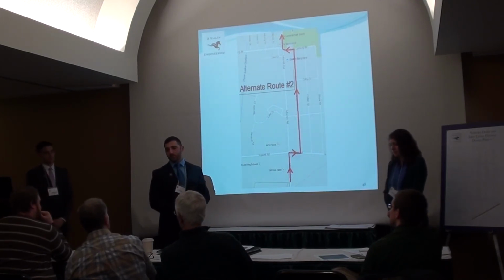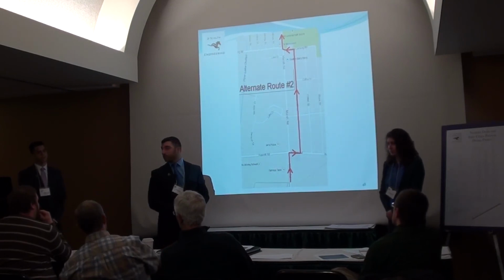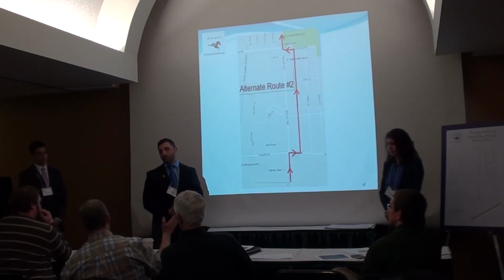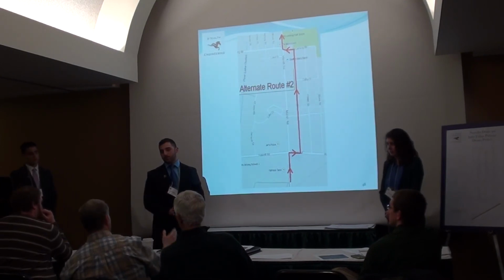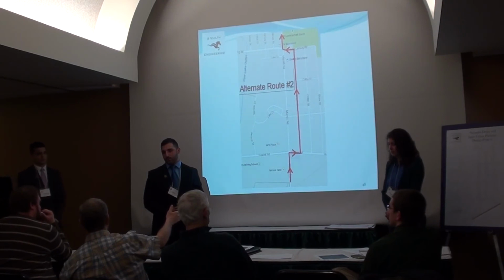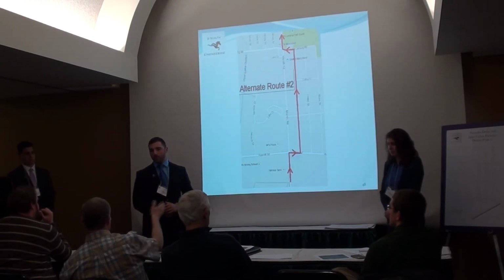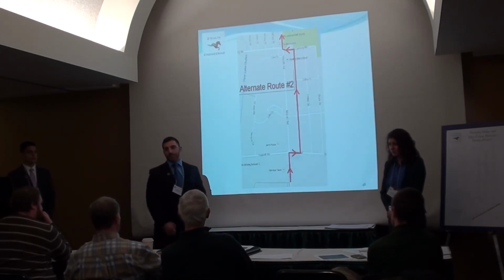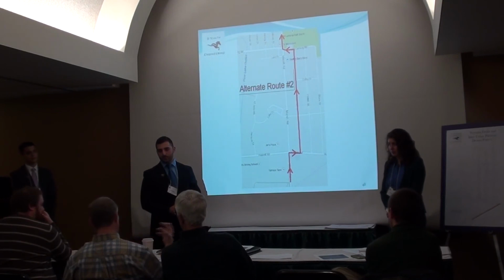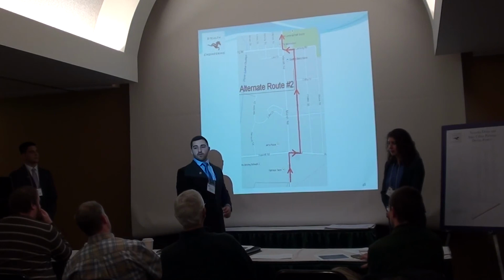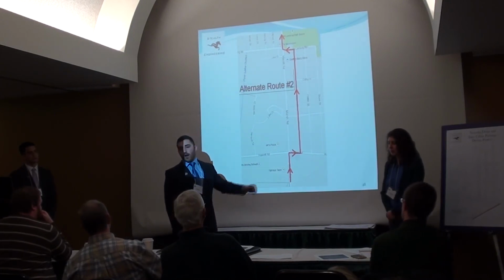One thing you want to consider in this is driver's ability to react. And now what you're telling me is you've got basically 3 alternatives at some point in time. There's a point where you're constructing Marsh, or conducting your work on Marsh, and you show a maintaining traffic detail, suggesting that you can still get traffic on Marsh, but now you can also go this way and also go that way. How much confusion do you want to generate at that intersection of Marsh and Hazlitt or Marsh and Lake while drivers decide what's going to be my best route? What do I want to do here?